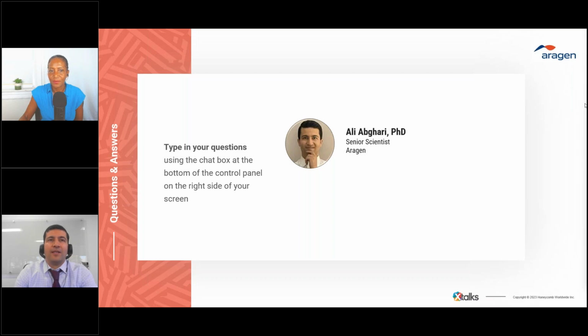Yes, there are a lot of factors that can affect the characteristics of our product. Some of those factors, I think I mentioned on one of my slides, come from the way that we set up the medium and the way that we set up the process, with a lot of different process parameters. They can affect the quality of the product. For example, sometimes we fine tune the dissolved oxygen. Sometimes we fine tune our feeding regime, or sometimes we go for a specific temperature shift in order to get a better product with higher quality out of that process.